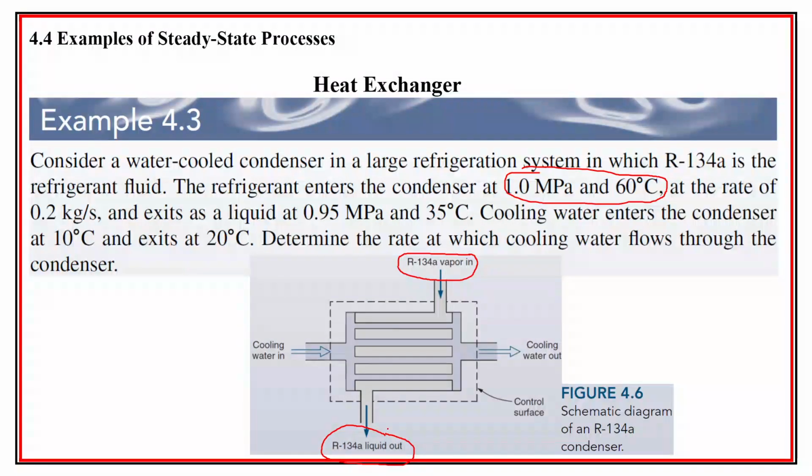One of the properties of refrigerant is that we can remove the latent heat of vaporization so that it changes from a vapor into a liquid, right? And doing that, we remove a lot of heat because it's not just reducing the temperature, it's reducing the phase. That's the latent heat of vaporization. It's a large amount of heat where it actually stays the same temperature and pressure for quite a while until you've removed enough heat, right?